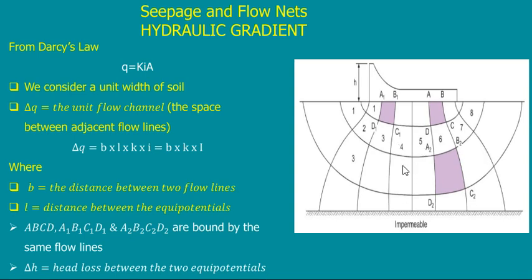I will consider this, suppose that I have here, go to the section in the middle line. This is 1, this is also 1, this is also 1. So this, I may consider it maybe 0.4 of a channel. As you see, it is subjective. If I say 0.4 and you said 0.3, who can tell me that I'm correct or you are correct? Nobody. It's something depending on judgment. So that's why flow nets is not very accurate because it depends on my accuracy.